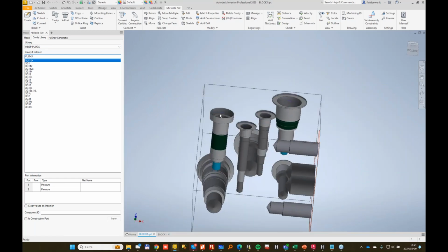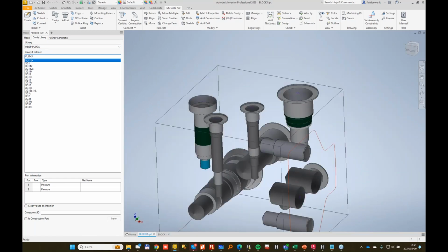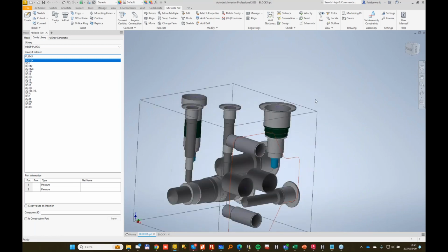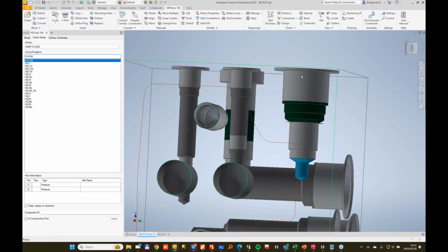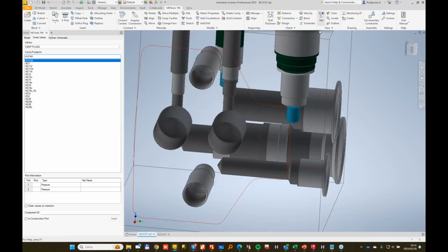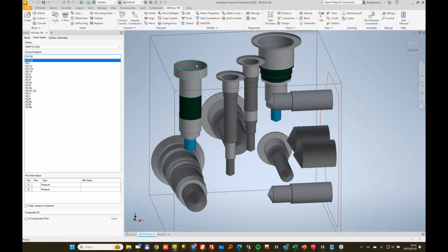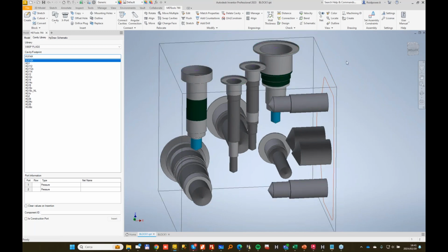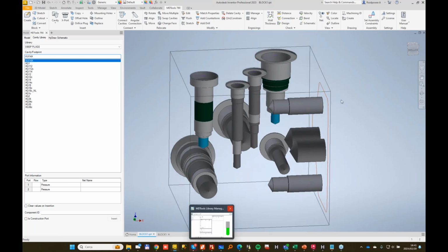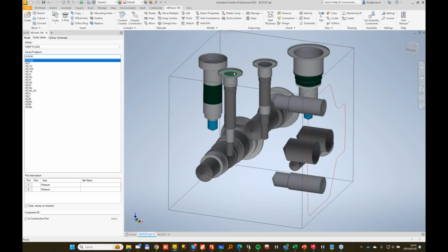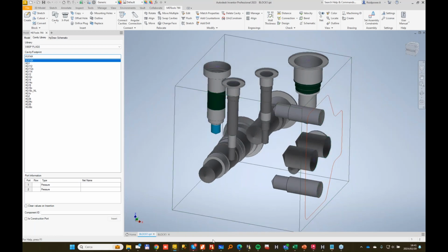So a check valve insert style, and there are similar flow regulator insert styles, may work in two fashions. One is when the cavity is placed inside a larger cavity, you can use the Orifice plug, and when the cavity is placed on the same thread, you will need to model a 2-way cavity. In my standard library, since I frequently need to use Orifice plugs inside a port, maybe you put an Orifice plug below a test point, I have, for simplicity, created libraries like this.